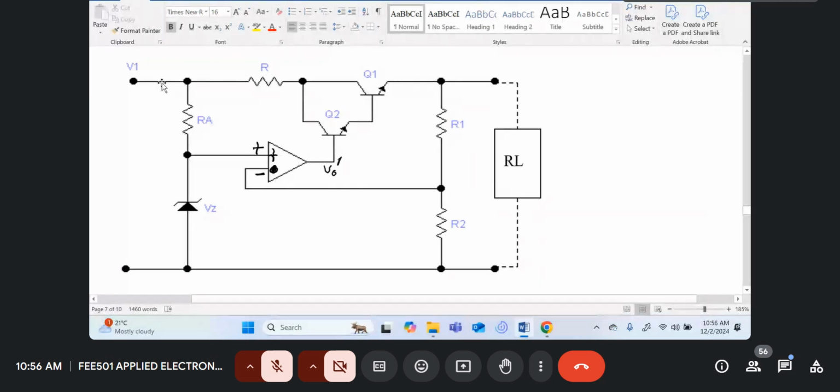The resistance looking back into our unregulated power supply. All power supplies have some internal resistance unless it's an ideal power supply, like the ones used in circuits. But most practical power supplies will have a resistance. Maybe it could be a milliohm or 2 milliohms or 10 milliohms. But there's some physical resistance seen going backwards.